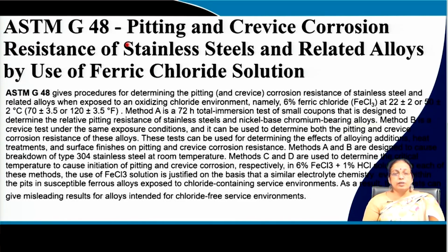The mandatory requirement is that you observe the surface and find out how many pits are forming on the surface, or what is the volume of the pits that are forming on the surface as a function of the time of exposure. On the other hand, if you would like to measure it electrochemically, there you try to find out the potential for pit initiation as well as the potential for pit propagation, the critical potential for pit initiation or critical potential of pit corrosion.